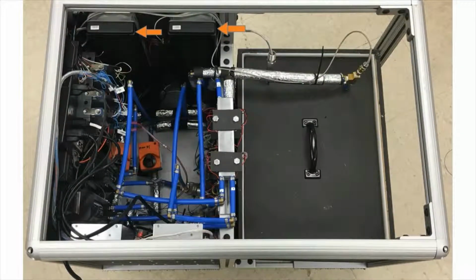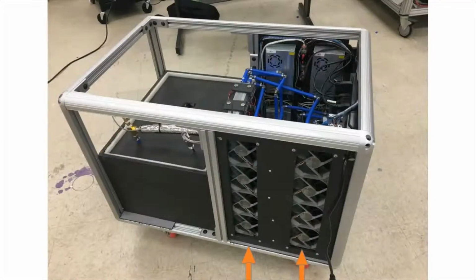These are our radiators. We use 2 blade and fin radiators. Air is forced around radiator fluid that is flowing through the small fins. This contact with the air forces heat to be exchanged between the ambient air and our radiator fluid. This is the outside of the radiators. We used 8 fans to force air through our radiators.